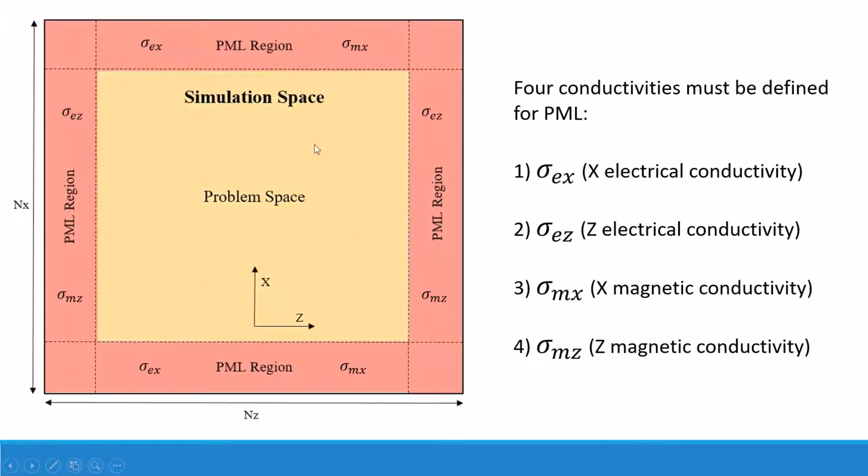What's shown here is the standard PML, so a very sudden change in the conductivity within the simulation space, typically 0 unless there is a material defined, and the PML region, so a sudden jump here. In principle, this shouldn't be an issue, and the FDTD should function normally with the PML implemented this way. However, in practice, it can cause some erroneous results and some imperfections.